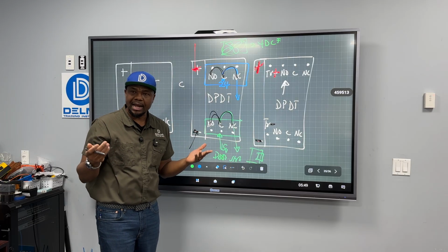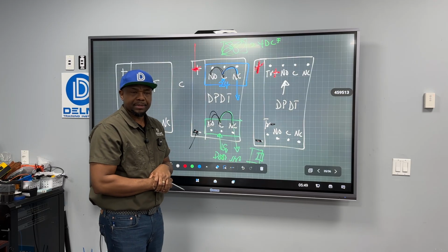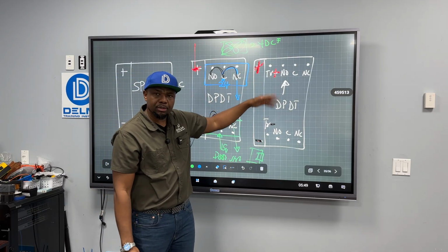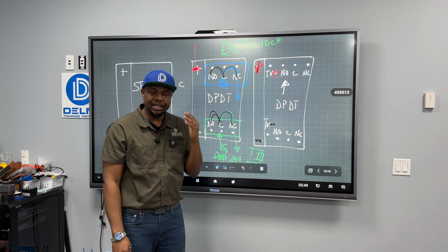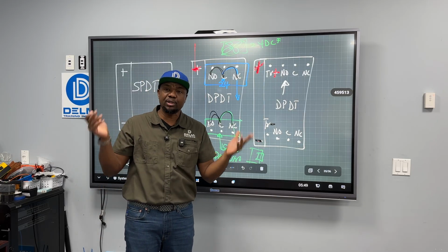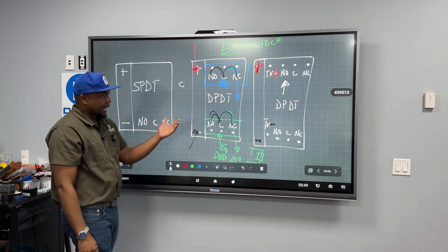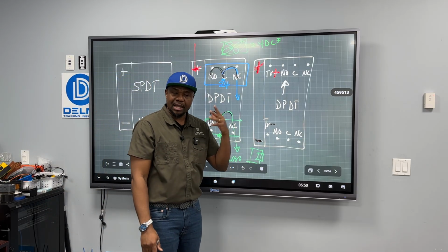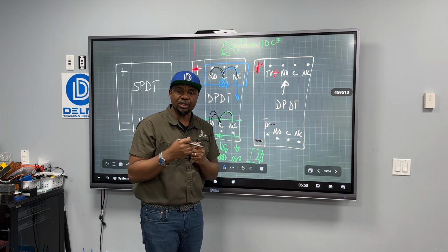And we're going to look at how we can wire each and every one of them. Remember, you use double pole, double throw relays if you have different voltages that you want to use, or you have multiple devices that you cannot connect here. Again, I can use this for the same voltage, 12 volts, but probably I have multiple things I want to connect.